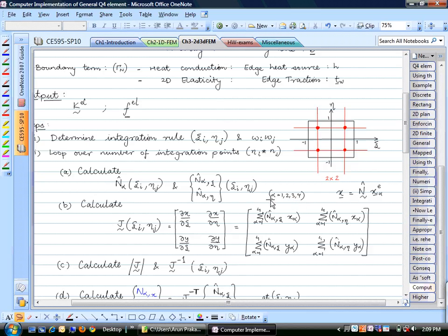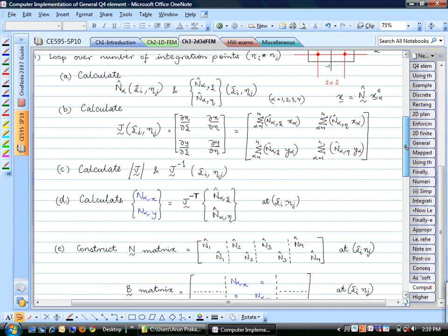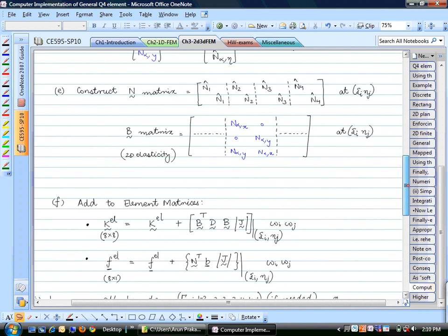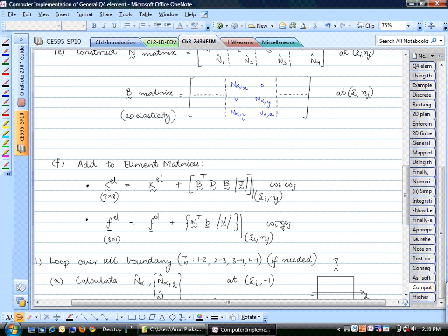So isoparametric elements can be really quite expensive to calculate when you're doing your MATLAB calculations. If you have even 1,000 elements, or even maybe a bigger mesh, let's say 10,000, or something like the mesh that I gave you, 2,000 elements, and you're doing this 2 cross 2 integration, that will take quite a bit of time to calculate. It will not be as fast as your CST elements. But essentially this is all just coding up stuff. What you need to understand is how this is all going back and fitting together in the original weak form.